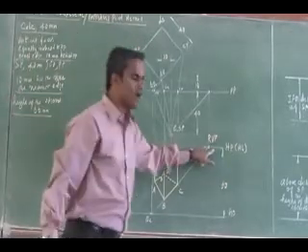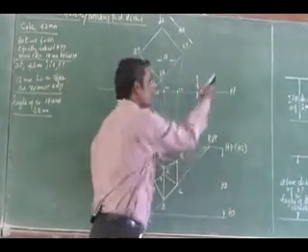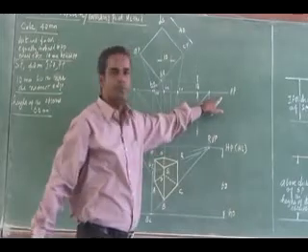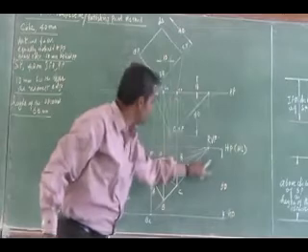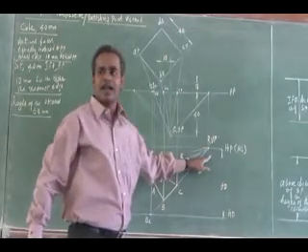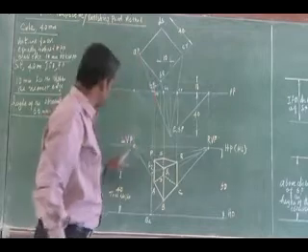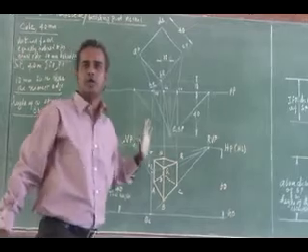The vanishing point you have to obtain carefully from the station point, parallel to one face, to the right side. I have to draw a parallel line to the picture plane. So draw a parallel line to this face, it will meet the picture plane. By dropping that to the horizontal line, that is my right vanishing point. Similarly, for the left vanishing point, draw parallel to this face and drop to the horizontal line, and I will get the left vanishing point. Is it clear? Have any clarification?